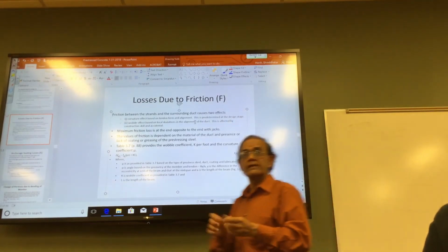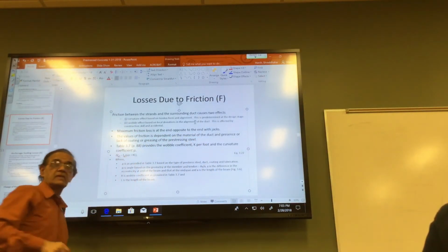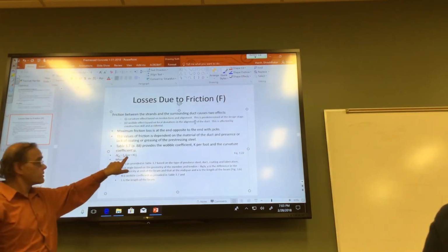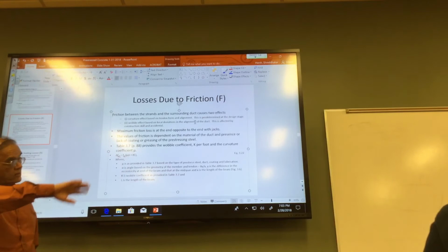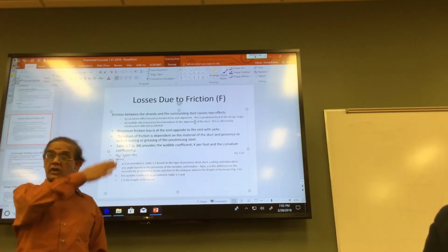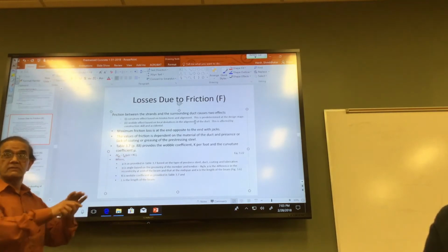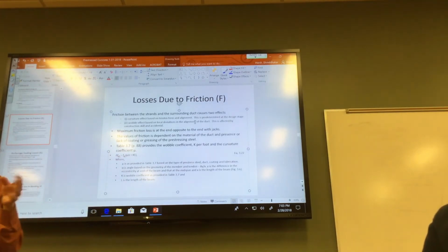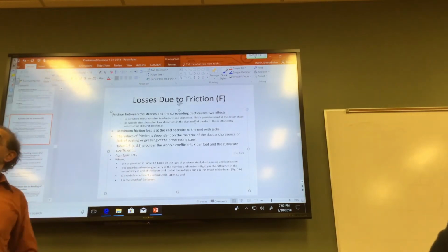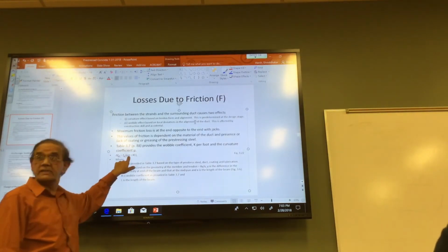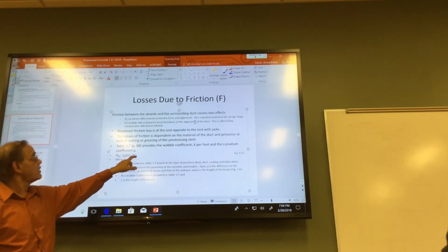As you pull it. So that's one part, which is called the mu alpha, where mu is the coefficient of friction that is given in the table. Alpha is the angle of the profile. So the sharper the angle, the bigger the angle, the more the loss, right? If the angle is 0, then this force can go away, right? If it is a straight tendon, no profile, then this will be 0. Alpha is 0, right?